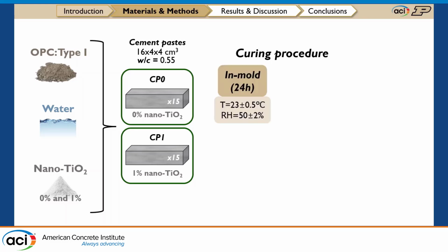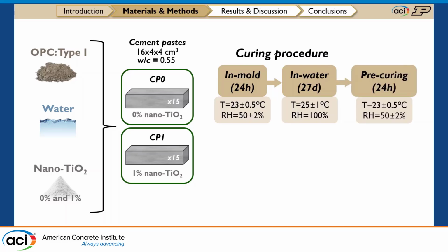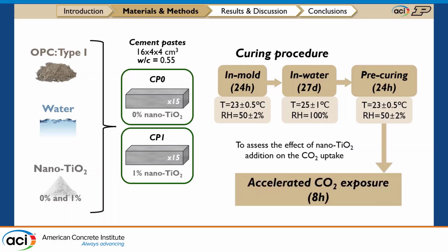For the curing procedure, we did 28 days of curing in water, and after that we did a pre-curing cycle to prepare the samples for the exposure to CO2. And in order to assess this effect of the titanium dioxide nanomodification on the CO2 uptake of the samples, we did an accelerated CO2 exposure of 8 hours.